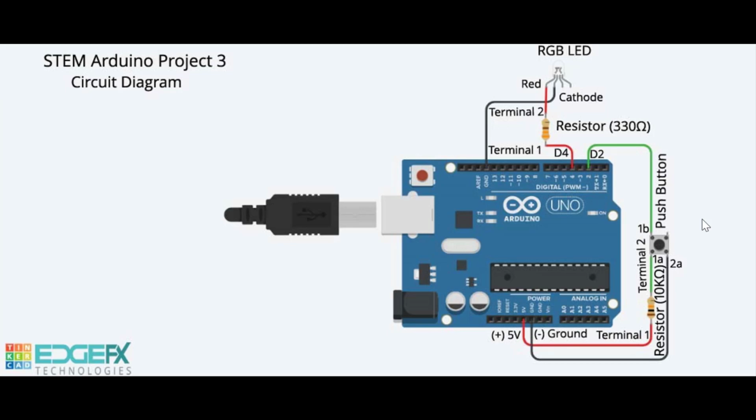Circuit explanation. The program is written in such a way that when you press the push button switch, the input pin D2 changes the state to logic low and the output pin D4 changes the state to logic high in closed path 2, and the red anode of the RGB LED connected to the output pin D4 then activates and deactivates periodically as per the sketch, finally giving a medium high-speed flashing effect with a red light.